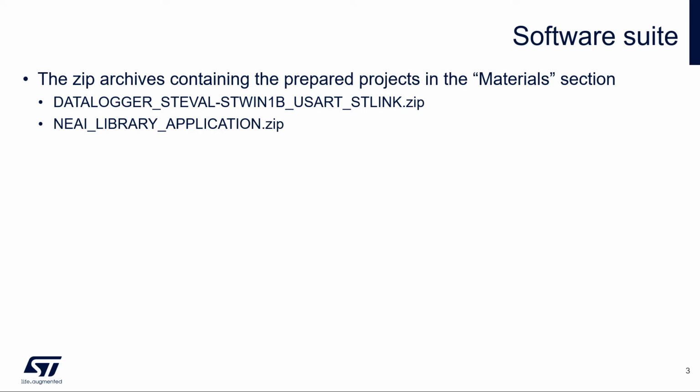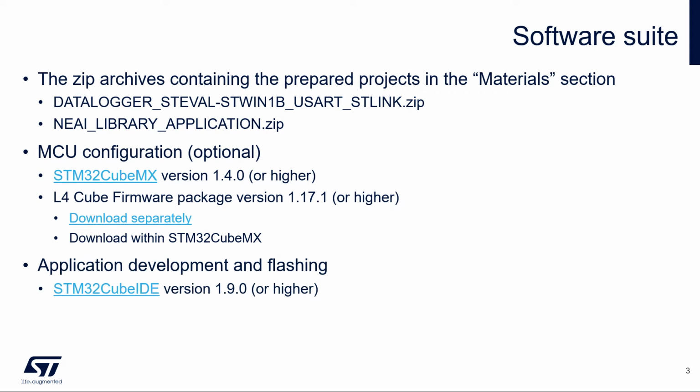In case you want to recreate this project, you will need also the CubeMX configuration tool. We use the 1.4 version, but a higher version will also work. And the associated Cube firmware package, the package that contains all the drivers for the MCU family, can be downloaded separately or directly within the STM32 CubeMX.